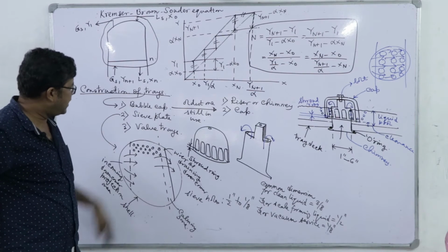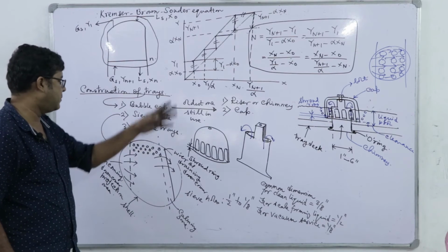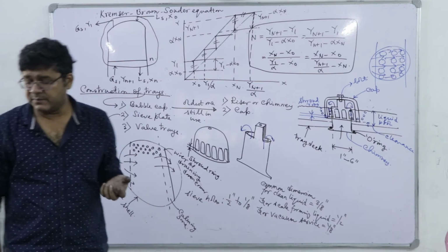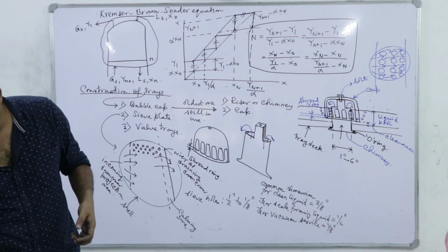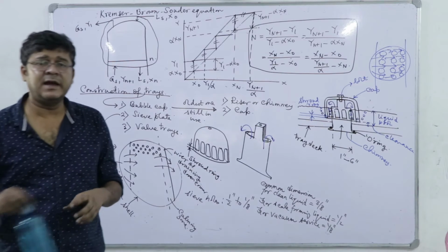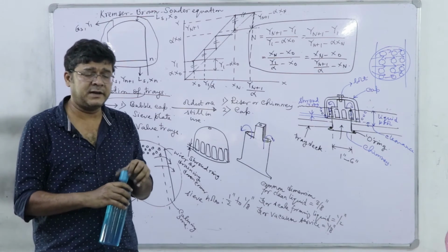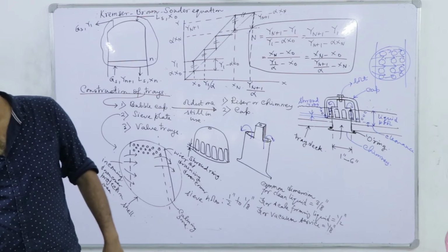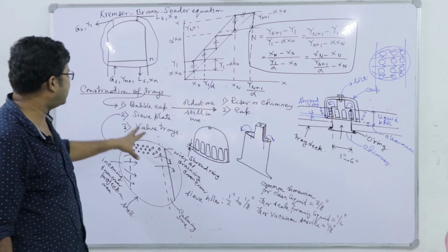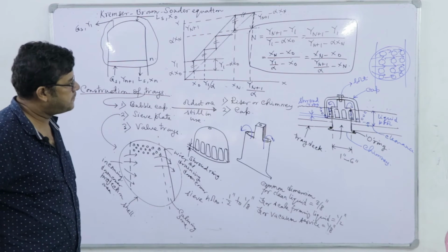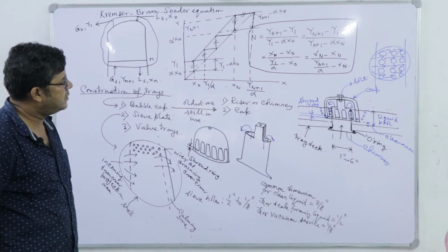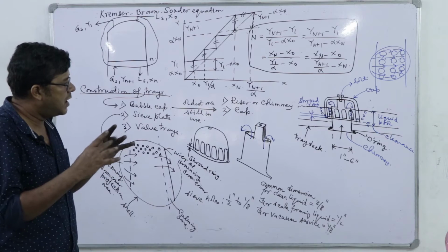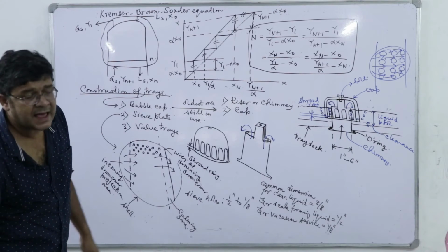So, that is the two classical types of these trays we use. One is a bubble cap, another is a sieve. Now, what is valve? Valve is relatively more recent type of tray design, and it is till date a proprietary item, that means it is patented. The valve tray has an advantage over this bubble cap and the sieve, as it offers nearly invariant gas phase mass transfer coefficient upon adjusting the gas velocity.